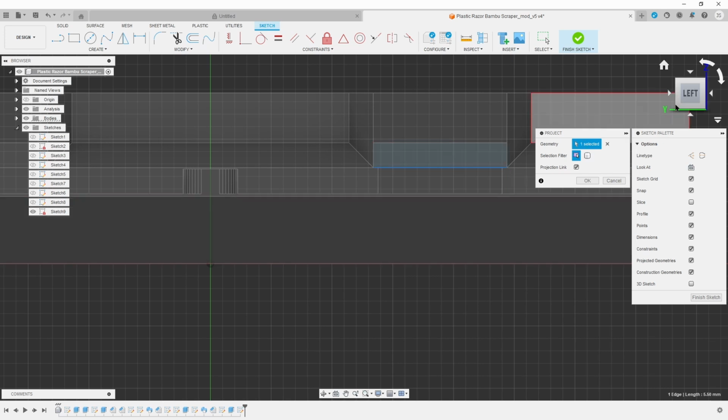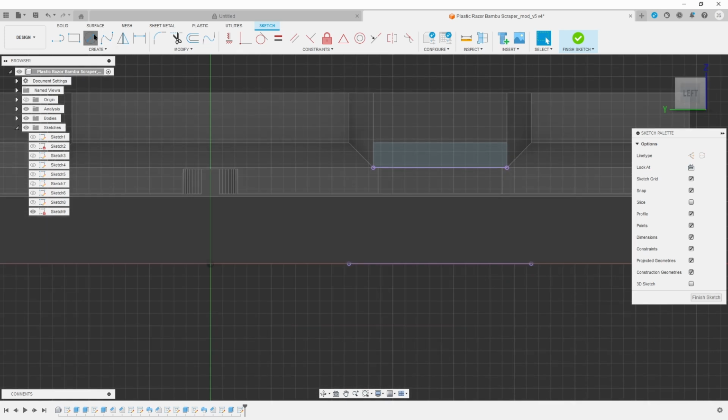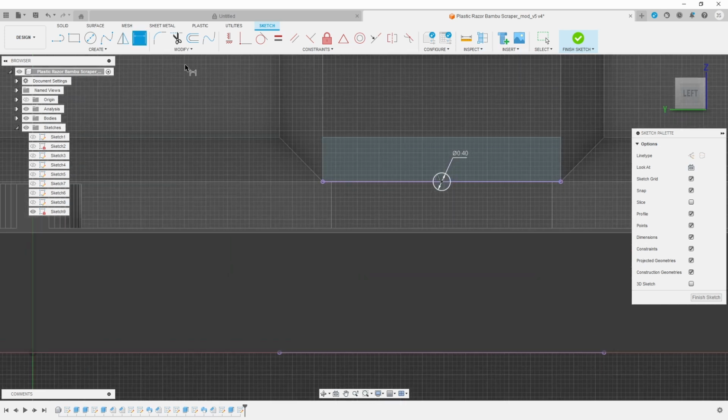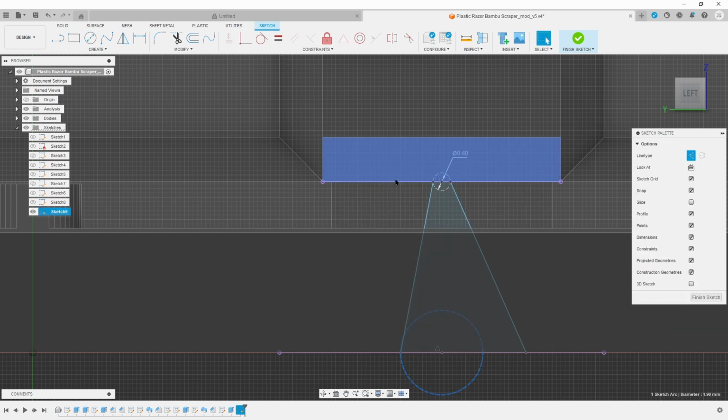So I've decided to add an additional feature that goes down the center of those pieces. So I have to create a sketch. One simple way of making sure that you have a centered sketch is to use a circle, right? Because the radius is always the same everywhere. So then I can tag off of the edges of the circle, and then using my circle again, I can find the midpoint of this feature and tie those pieces together with coincident mates, and turn the circles into construction geometry by using the X key.